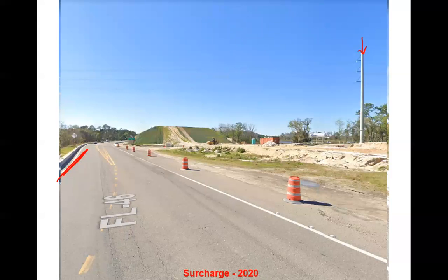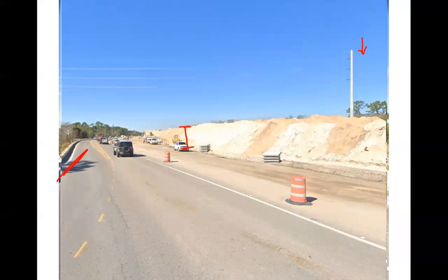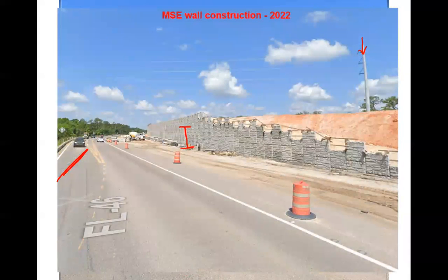But what you'll see is that this is actually taller than the roadway is planned. So they need to bring in fill to this project site anyway. So what they do is they concentrate it on this area that has organics, so then they can do the rest of their site prep. They can compact, they can start moving utilities around and stuff. And eventually they use that fill to create the entire roadway. Then you see them starting to build the stuff that actually looks like it, with the MSE walls and all that stuff.